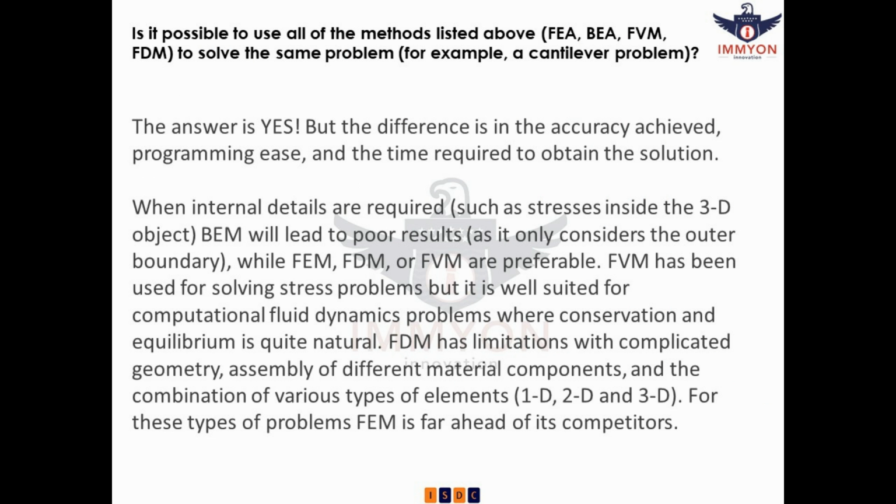Question: is it possible to use all of the methods listed above, FEA, BEM, FVM, FDM, to solve the same problem, for example, a cantilever problem? The answer is yes. But the difference is in the accuracy achieved, programming ease, and the time required to obtain the solution.